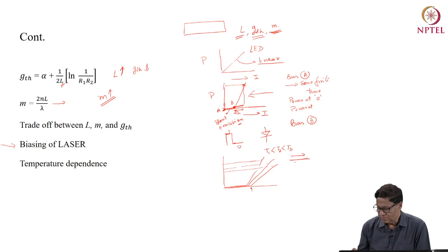So there are some techniques which make the junction temperature constant. One of them is the use of a thermoelectric cooler. It basically senses the temperature and accordingly pushes more current or less current depending upon the temperature, and the power output is held constant. So this is highly temperature dependent, and some mechanism should be there to arrest this variation in power with respect to temperature.